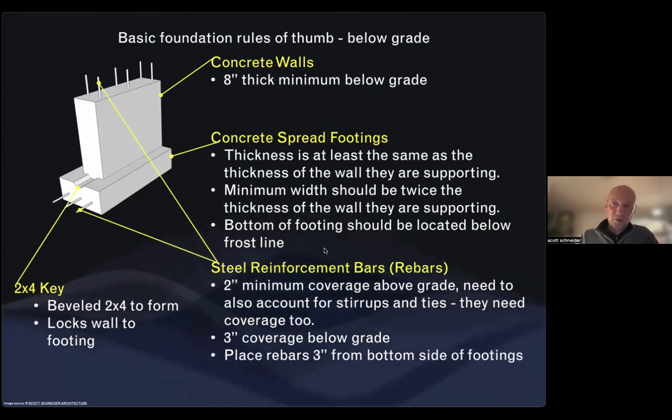That includes stirrups or ties, which have to also be fully covered by that 2 inches or 3 inches. So your rebar may actually be set further in, is the point of that.